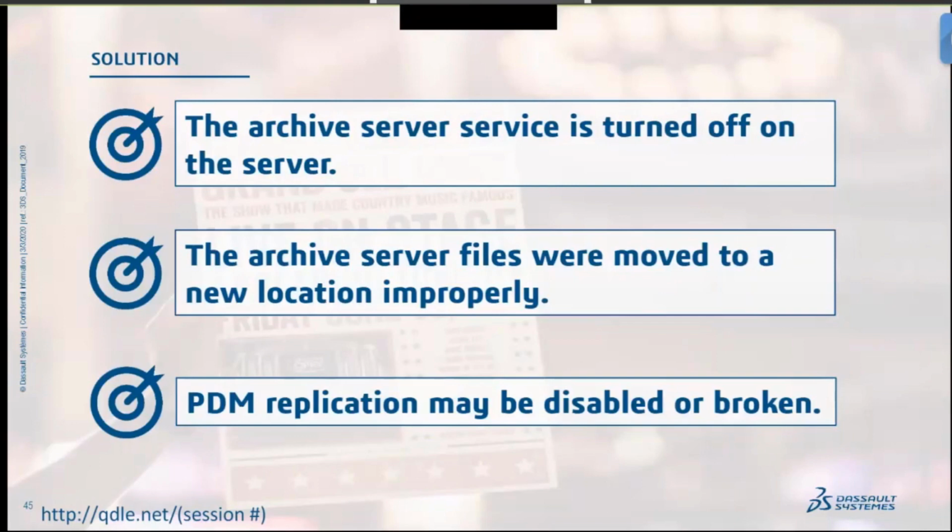Another possible reason for this is if you are using PDM replication, if you have multiple sites that are utilizing PDM and we're replicating this data from one site to the other, there could be an issue with the replication, where maybe it thinks that that file is replicated to that second site, but no actual file exists.